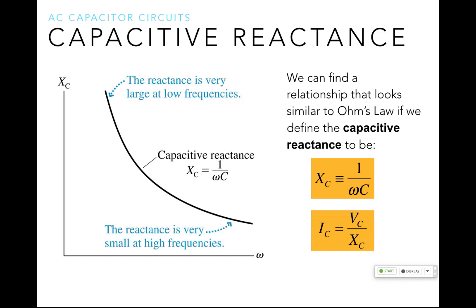Now, these are the maximum current and maximum voltage. What do we know about the instantaneous current and voltage? Can you use V equals IR for that? No, why? They're out of phase, right? So do this and this happen at the same time? No, okay? These things peak at different times. So this only works when you use the maximum values.